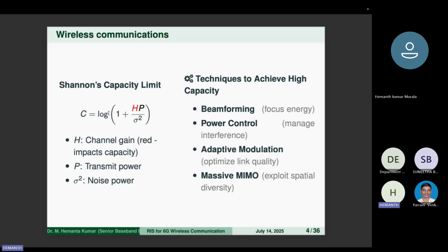Here I am using 4 antennas, and 4 antennas will be transmitting. Before transmitting, self-interference will happen. The same signal interferes with this antenna, this antenna will interfere with that antenna, and so on. Then overall interference will happen. That's why we are not using massive MIMO in such systems. But in 5G, we are using massive MIMO, and practically a maximum of 64 antennas is supported. So that's MIMO.